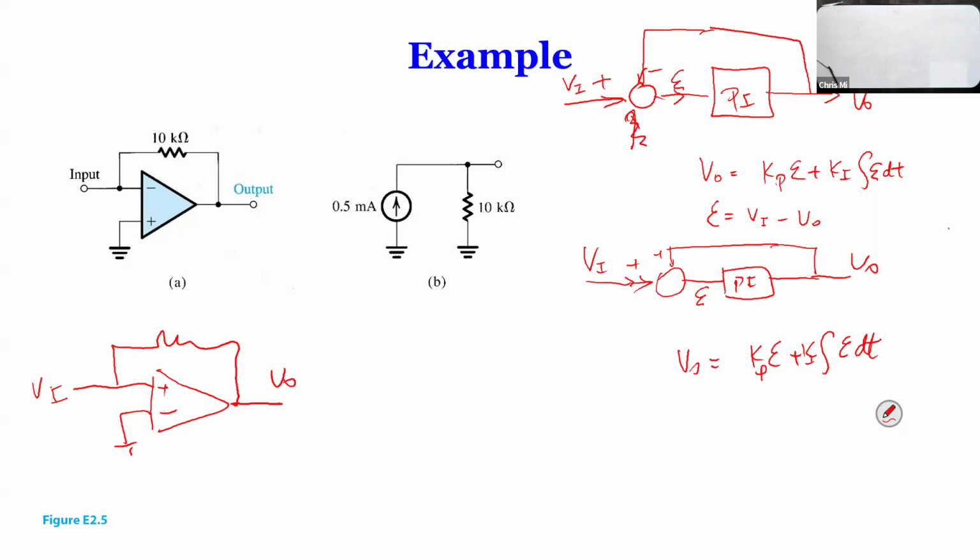Yeah, go ahead. I was still a little unclear about the point of feedback. We want it at the negative terminal so it subtracts. Right. The feedback tries to maintain a certain output, because the gain is so big. Say the gain is infinity right now, but let's say it's not, let's say it's 10,000. If you have a 1 millivolt input, what happens to your output? It's 10 volts. You have a power supply of 5 volts, so you're already saturated. You can only get 5, right? So that's kind of unstable.